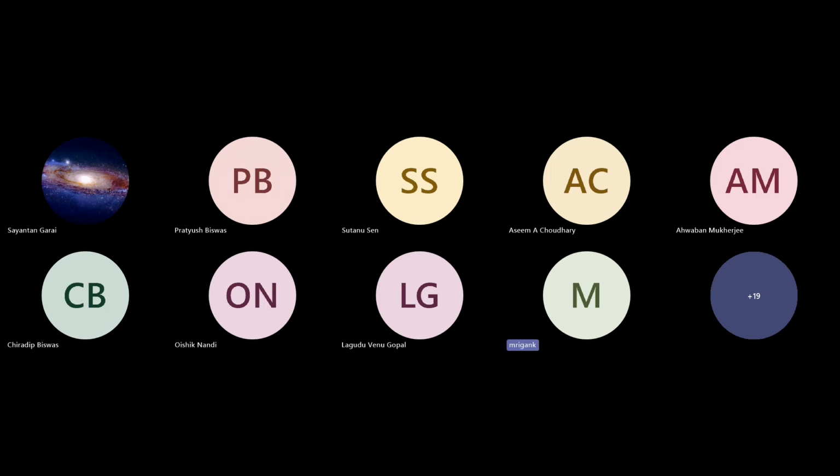So the dynamic one without the preamplifier, eventually it should go to one of the values, right? Either it will go to VDD or ground. It cannot stay in between, because the latching operation is always there. If your signals are too close, both the signals are exactly equal, or you are keeping them very close, and the resolution of the comparator is not that good, then it may take a lot of time to settle, but eventually it will settle to one of the values. It is possible that you may be simulating with a higher clock frequency. If you simulate with a lower clock frequency, probably it will settle.